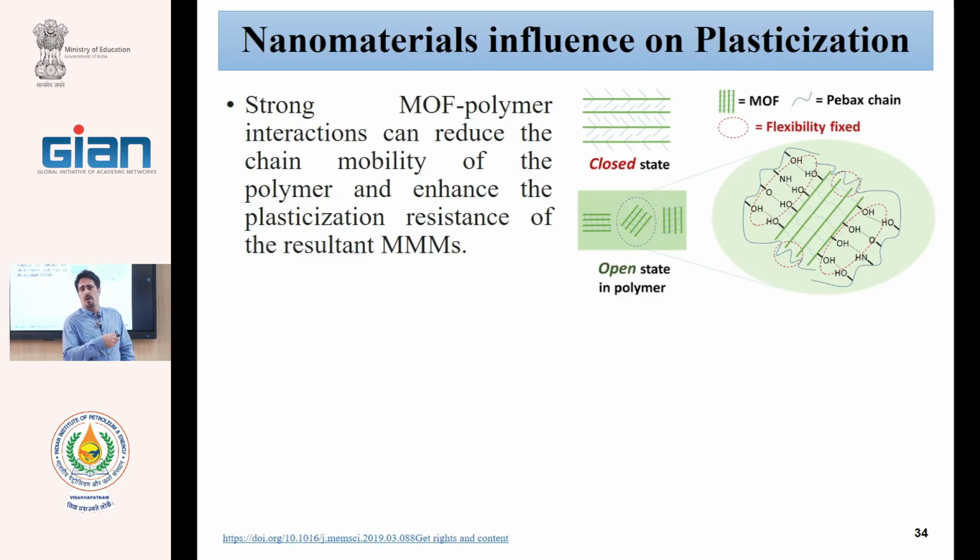With the addition of nanomaterials, in this case, we increase the long life and reduce the plasticization. The insertion of the nanoparticles can interact with the polymer chains and not allow them to interact with the gas. Mostly carbon dioxide causes the plasticization.